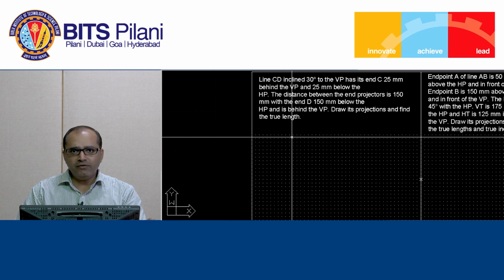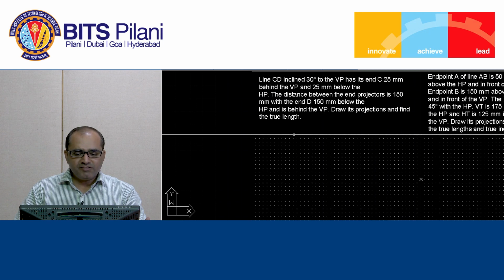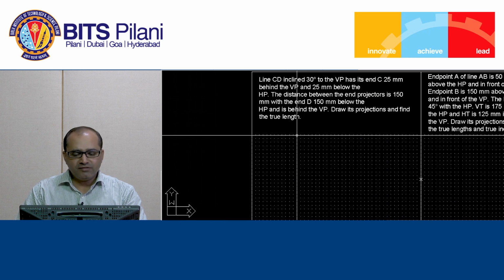That means we divide one AutoCAD unit into 4 parts, and we take one AutoCAD unit is equal to 100 millimeters. Since we divide it into 4 parts, the distance between each grid space is nothing but distance between 2 dot points, it is 25 millimeter. So our unit will be the distance between two grid points, that is grid spacing, is equal to 25 millimeters.